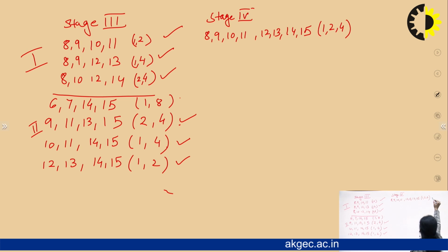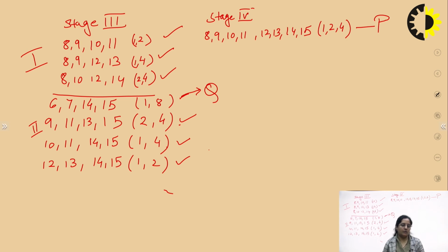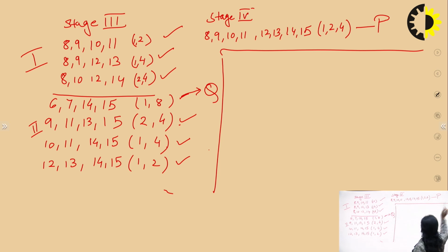So this is my prime implicant, which I can name P, and you will find that this number remaining here we can write as Q. All the rest of the minterms are covered. So we obtained 2 prime implicants from this reduction method, or tabulation method, and now we have to prepare a prime implicant chart for this case. In the prime implicant chart, for the first case we write P.